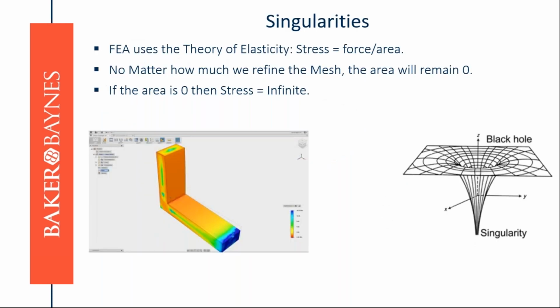Now, another thing that comes to mind, which I thought I'll share with you, is the stress singularities. Now, stress singularities are things that appear when we run an FEA. Often what happens is it happens on areas that come up on the model. So simplifying the model always helps sometimes. If there's a sharp curve or an edge or something that causes the issue on one of the axes or on the planes, you get a stress singularity that comes up, right?